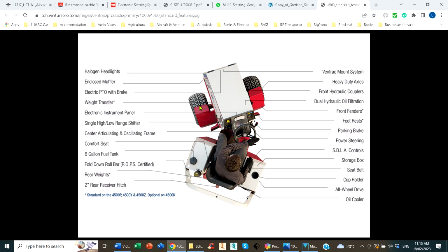Now that means that this axle here is a rigid non-steering axle, and as is the back, rigid non-steering axle. Removes the requirement for CVs and lots of other things. And in this case, blended into the steering or the joint is also the roll articulation, so that it acts as suspension.